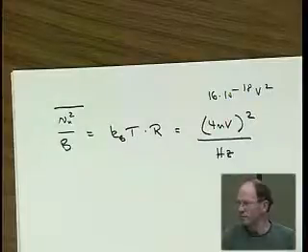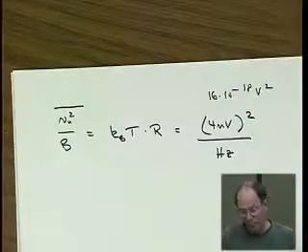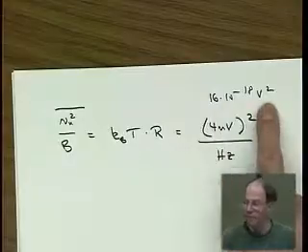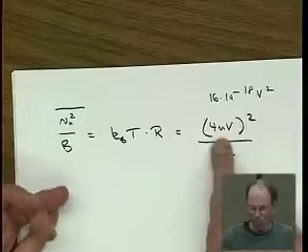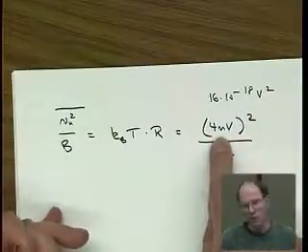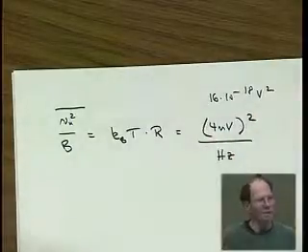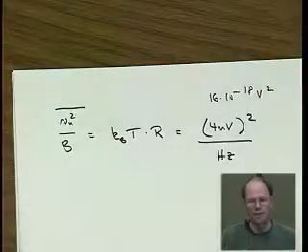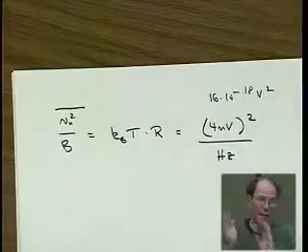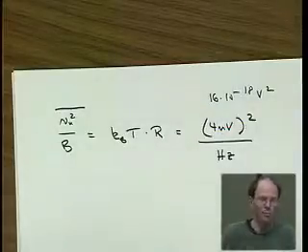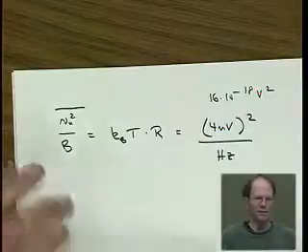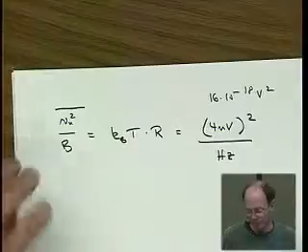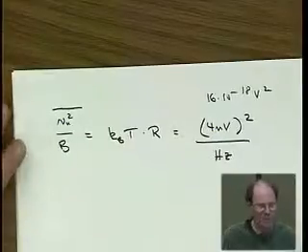Well, that's a little problem if you're plotting noise in the V squared form, because that's very common. The minute you take the square root, you get rid of this issue. But if you see something like that in your post-processor, check whether your post-processor is clipping and the noise is actually smaller, but the post-processor insists that something that small cannot possibly be the right answer and adjusts it for you, makes it a little bit bigger. Well, thank you very much.